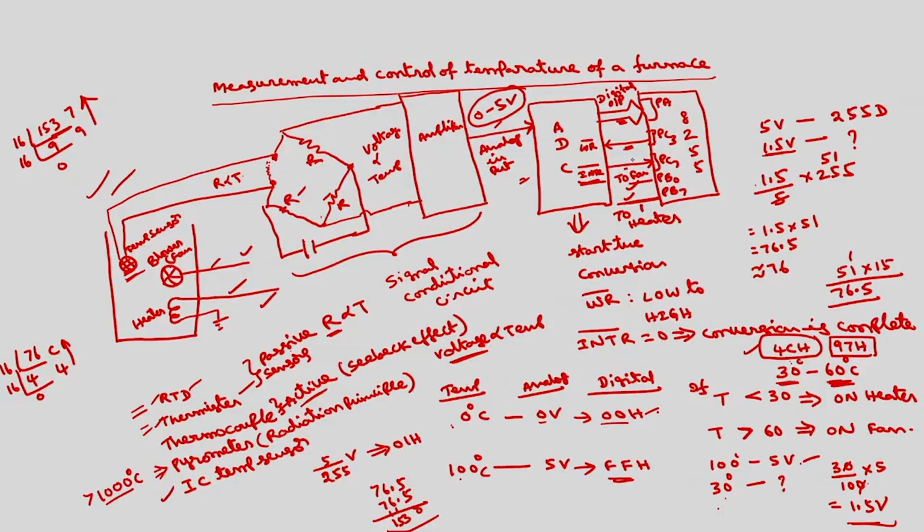So what is the control register for this? If you want the control register in I/O mode, this is for port C lower. Port C lower we are using as an output port, so this will be 0. This is port B. Port B also, you are using these two pins as output, 0. This is the mode selection for port B. I am using mode 0.